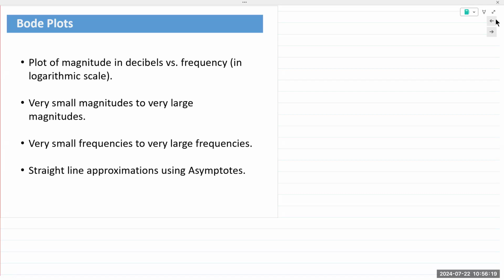You're transmitting a signal from one end to another, from point A to point B over very long distances. So there would be a loss of signal, a loss of power during the transmission. So when you sent a normal signal from one end, it's going to travel over tens of miles, reach the far end, and you'd be measuring the signal in probably milliwatts or millivolts. So engineers working with very large frequencies and very small magnitudes of voltages and power had a frequent problem of trying to actually plot these on a single chart.